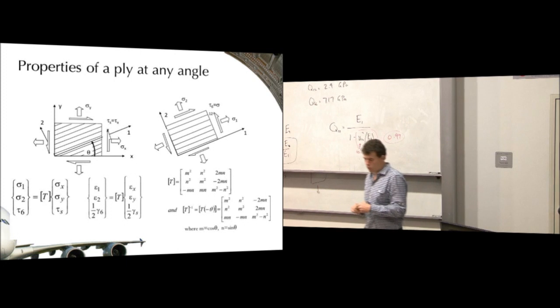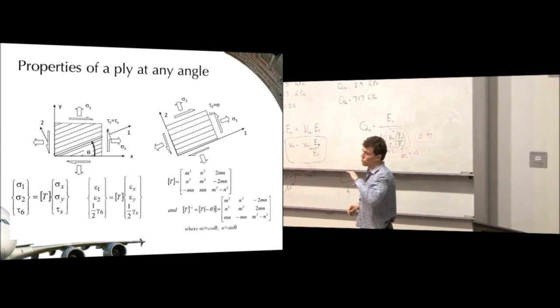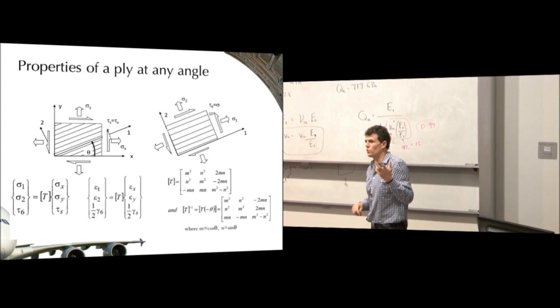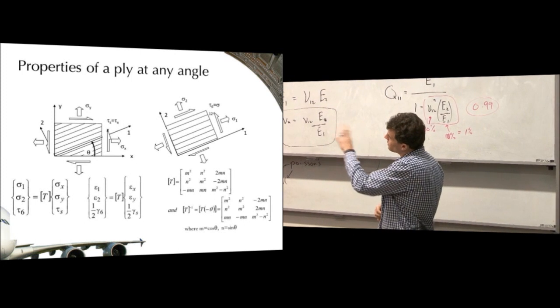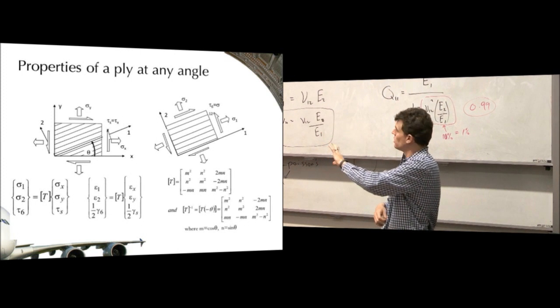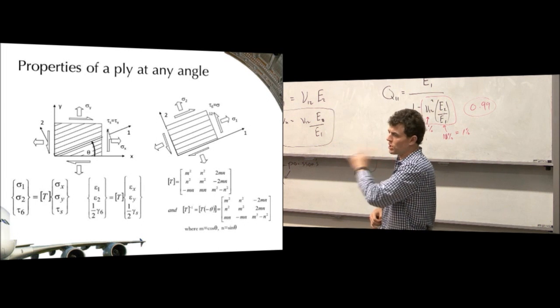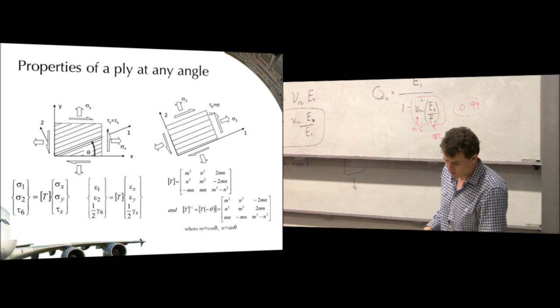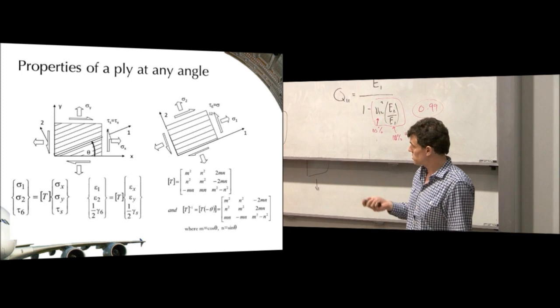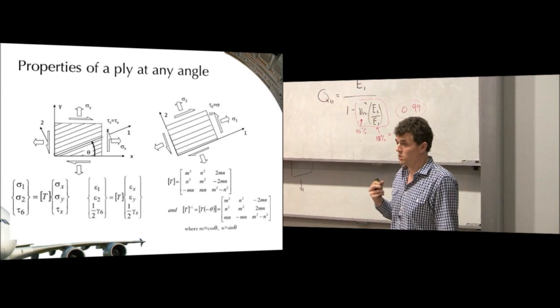And just like we do Mohr's circle, we can do the equivalent of Mohr's circle with an orthotropic material. It turns out that the maths I'm showing you here is actually just a generalized form of Mohr's circle that you wouldn't have been aware of, because second year teachers are too worried about introducing matrices.